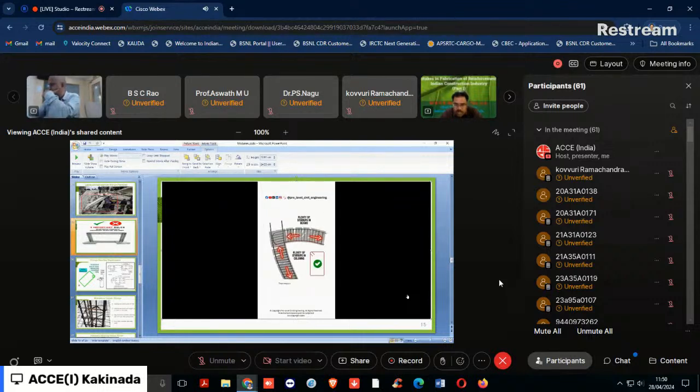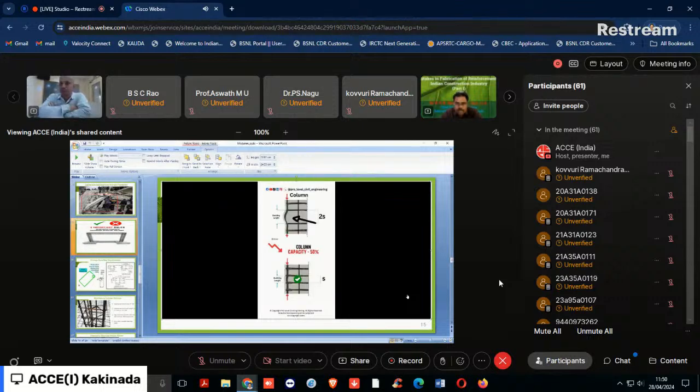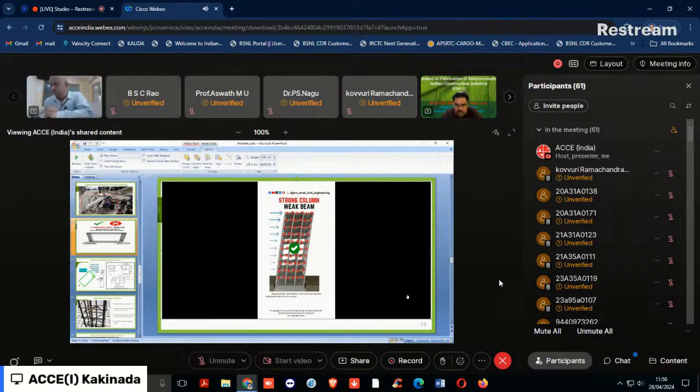2. There must be plenty of well-anchored stirrups in columns and beams to resist high diagonal tensile stresses and cracks and ensure ductile behavior. Eliminating one stirrup can reduce the column capacity by 50%. 3. Strong columns, weak beams. In the case of an extreme earthquake where failure is unavoidable, we prefer the beam to fail. Column failure could lead to complete building failure.